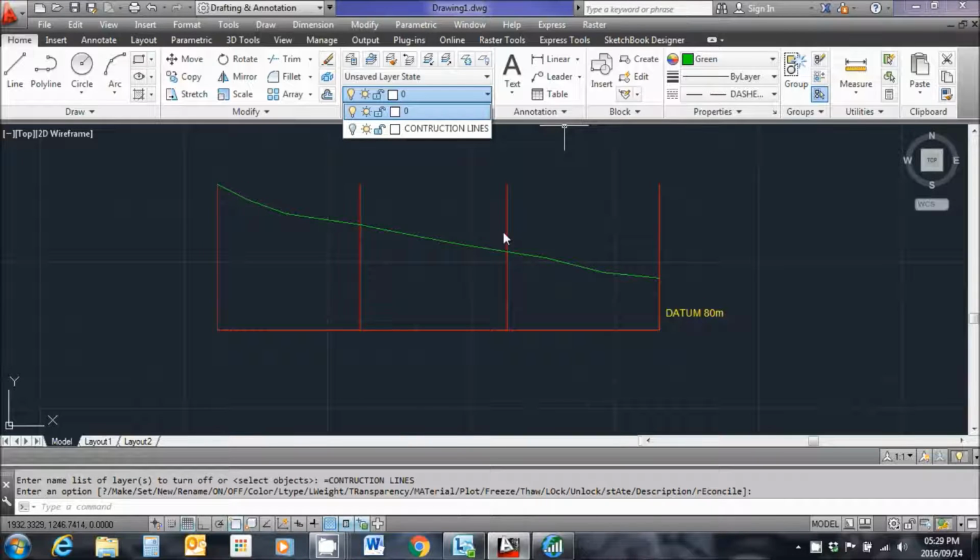Okay, so the next step then is going to be to draw in the sewer vertical alignment based on our ground profile. So in order to do that, we're going to set some constraints. I'm going to say, for the purpose of this tutorial, that the sewer line cannot be shallower than 1 meter below ground surface, which means that the sewer has to be deeper than 1 meter.